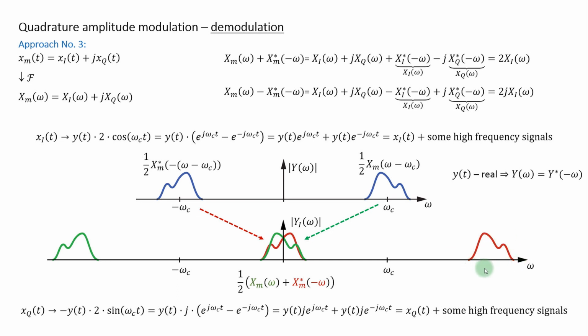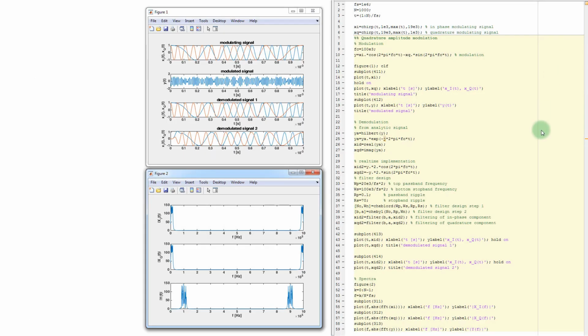These are the high frequency components that we want to suppress, so if we set the bottom of the stopband of our filter to the carrier frequency, the filter should suppress these high frequency components nicely. And that is what I have done here. The carrier frequency is 100 kHz and the bottom of the stopband I have set to 100 kHz as well. This division by the sampling frequency and multiplication by 2 is just a scaling that Matlab requires for these